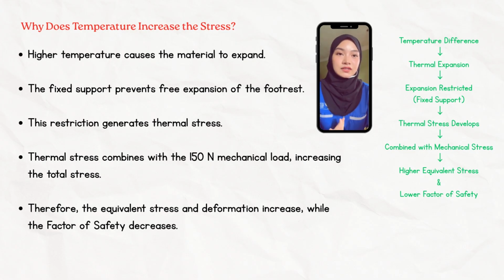This happened because the material naturally expands when the temperature increases. But in this model, the main tube is fixed and cannot expand freely because the thermal expansion is restricted. Thermal stress is generated inside the structure. This thermal stress is combined with stress caused by the mechanical load of 150 newtons. As a result, the equivalent stress and total deformation become higher while the factor of safety becomes lower, which is not safe.